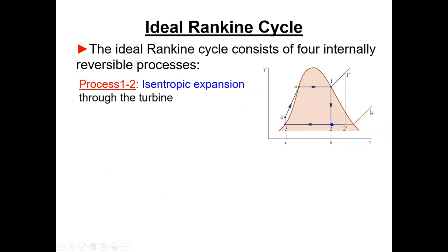That's a line of constant pressure on a TS diagram. Likewise, this is the condenser pressure down here, and it's the same, and actually it trails off over here into the compressed liquid region as well. They just didn't draw it. We're saying isentropic, and this axis is entropy.